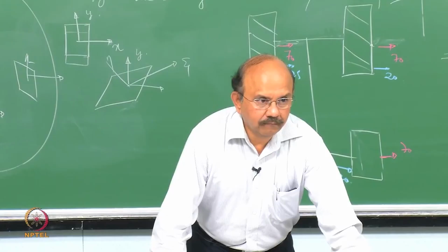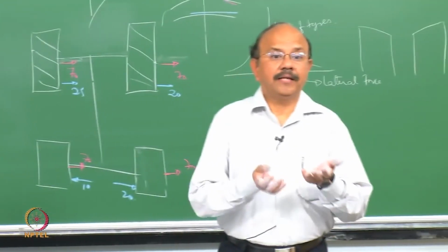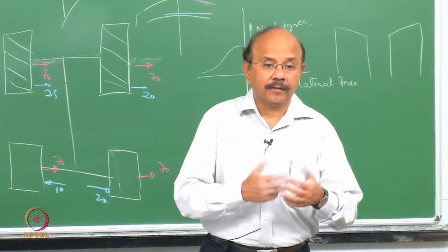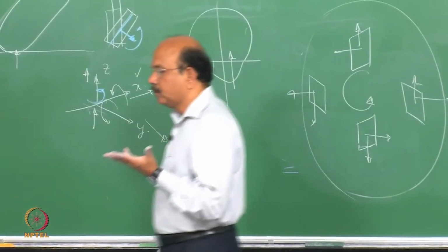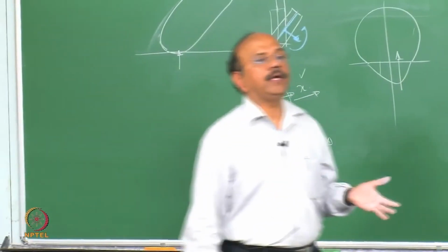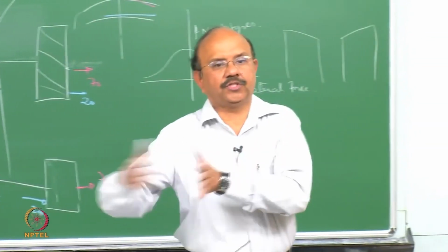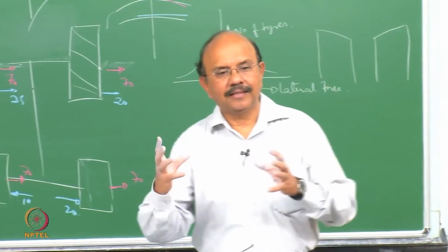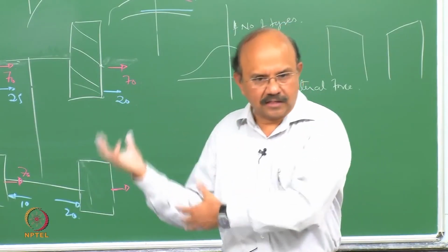Will that unloading and loading be constant throughout the free rolling? Like, suppose the contact patch will be. Yeah, but the graph which I drew was for a point. The question is, how do we view this loading and unloading? View the loading and unloading from the point of view of a tread: go and sit in a tread and look at it. Actually, the tread is at different positions in the contact patch. Maybe we'll do that in the next class. Then you see that each one of these points will get loaded and unloaded, and that's the graph which we saw.